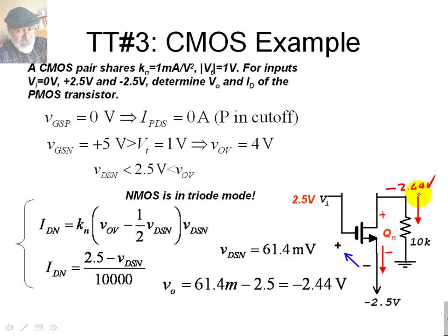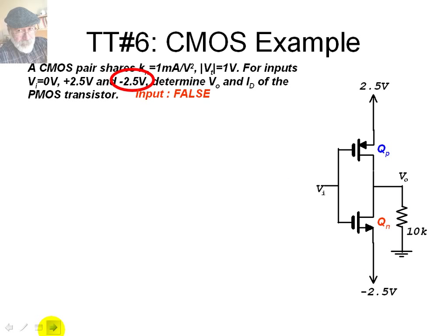But that, according to our rules, is below negative 2 volts. This is a false value, false. So that means that in this circuit, when we enter a true, the output is a false. So far so good. This is half of the behavior of a NOT gate. What else do we have? The input is true, the output is false. Let's try now with an input that is false.